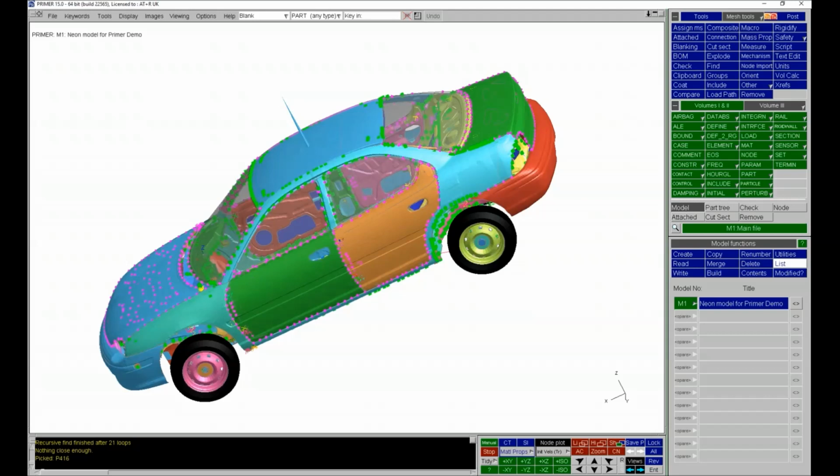Next question is, what is a NaN error? If you're talking about a NaN error in Dyna, NaN is not a number. And you get that when Dyna has crashed for whatever reason. I don't know why Dyna would crash in that particular example, but essentially it's doing some calculation where a number that it expects to be a number has for some reason become not a number.